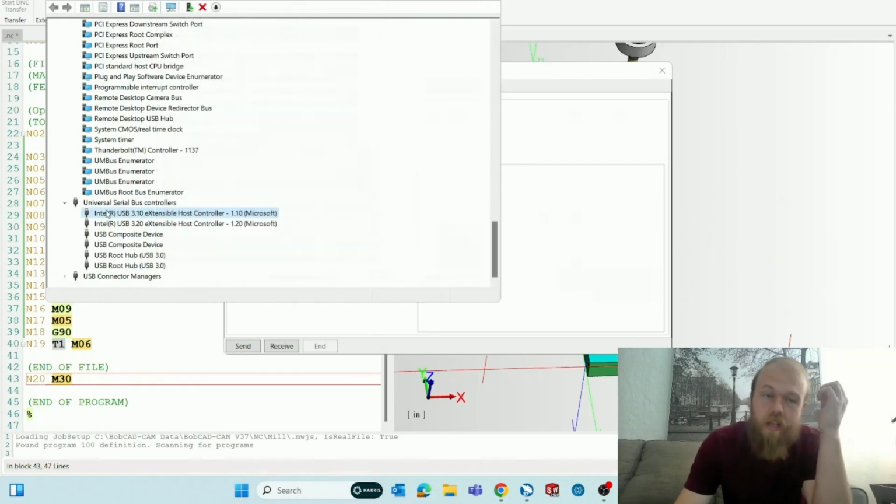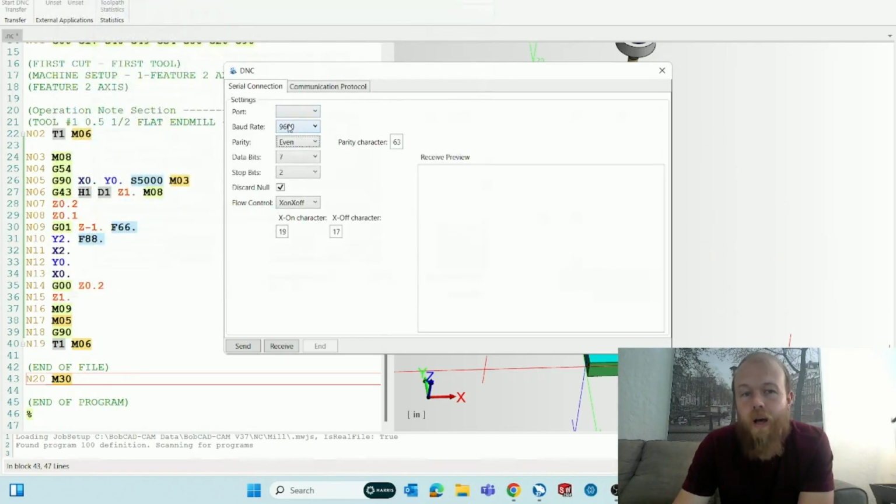But if you double click on the hardware or firmware, let's say it was port 1 from your USB to the 9-pin connection, you'll double click on it here, and then it will have the same port number, baud rate, and other settings that you have to have set up at that location and at this location, the same exact settings as they are at the controller.